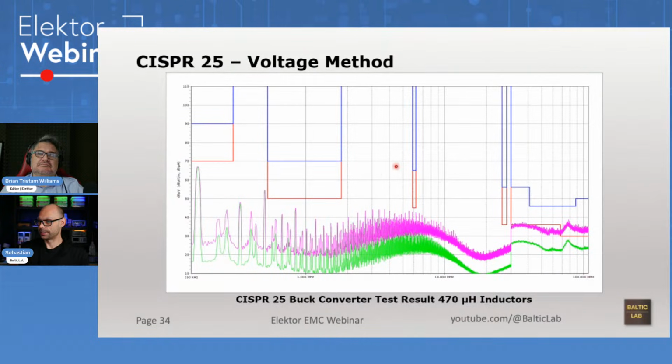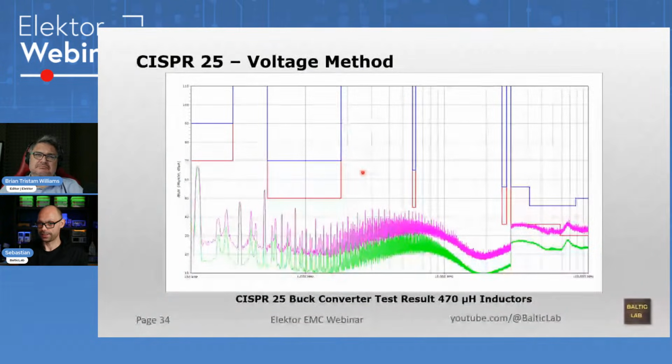Remeasuring, these are still CISPR 25 class 3 limits. And look at that. That's all we need. Like I said, it's a shame because I was kind of hopeful that I needed higher order filters, but I don't. That's it. Problem solved. Now we can go for compliance testing.